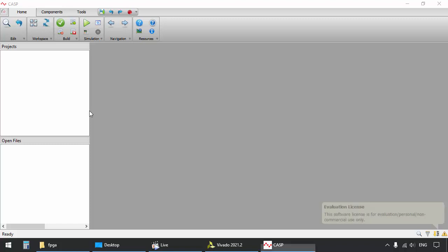This video shows how to get started with Xilinx Zynq SoCs. Before starting, Digilent drivers and Xilinx Vivado and Vitis software tools shall be installed. PCAP drivers shall be installed for Ethernet communication. CASP board support package for Xilinx FPGAs shall also be installed. Please refer to our earlier tutorial videos on how to install board support package and get started with FPGAs.